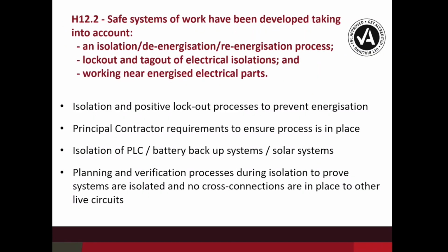12.2 then goes into our lockout tag out. So isolation, de-energization, lockout tag out, and then re-energization at the end of that process. That circular loop is quite often missed in terms of the steps that are required to identify the necessary circuits, to turn them off, to make sure that the electricians have physically prevented those circuits from being re-energized. So it's not just a case of switching it off and putting a little bit of tape over the circuit breaker and things like that. They physically have to tag these out, put an isolation tag, and put a lockout on it to prevent that from being turned back on again.